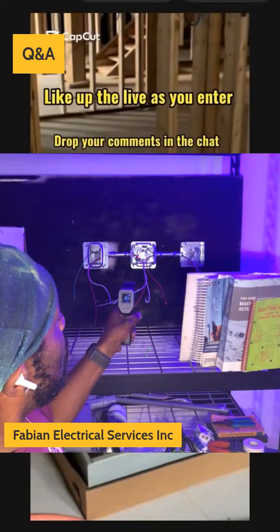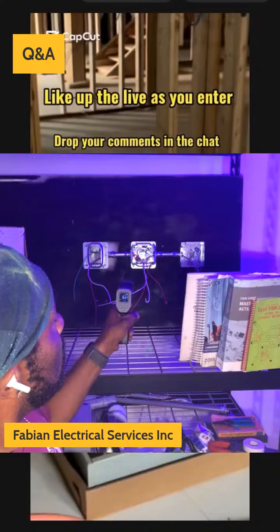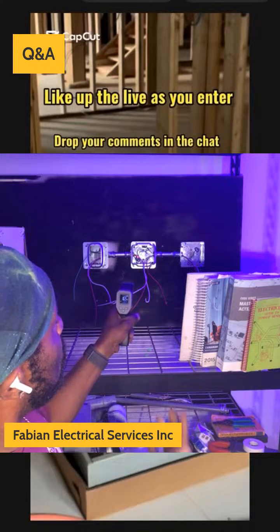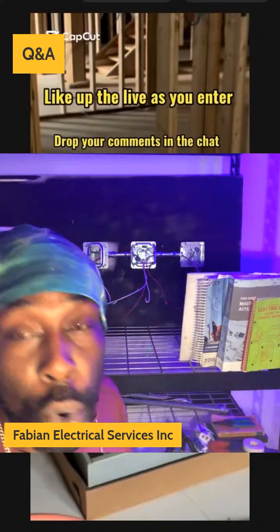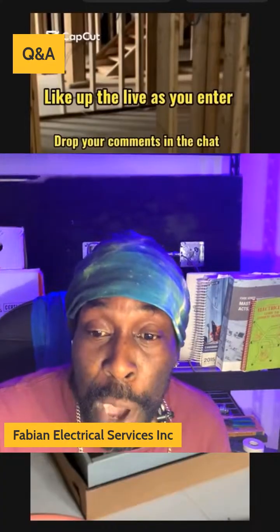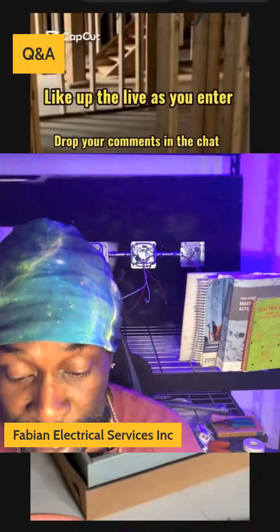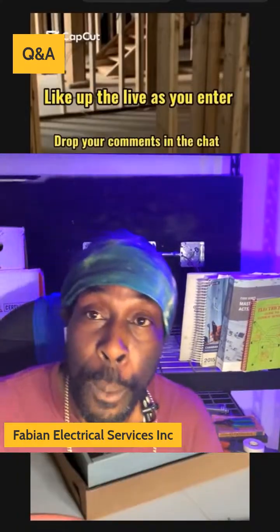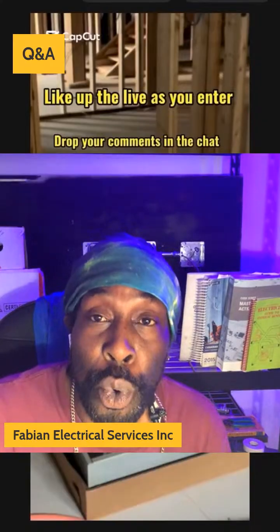Also, you can do that with the wires itself. You can simply scan your wires with the infrared thermometer, and it's going to tell you if those wires are rising in temperature or overheating, and so on. So that is how you would go about using your infrared, and also how you would make sure that your wires are not crammed and overheating.